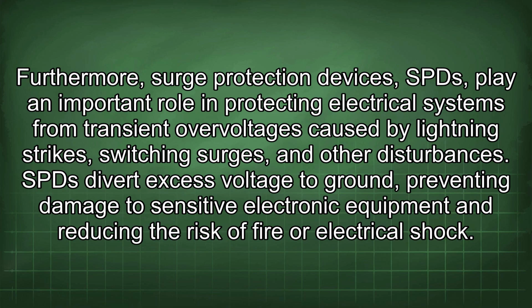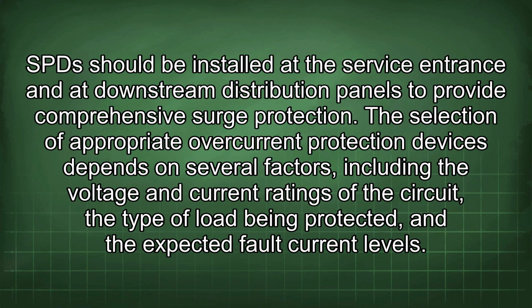SPDs divert excess voltage to ground, preventing damage to sensitive electronic equipment and reducing the risk of fire or electrical shock. SPDs should be installed at the service entrance and at downstream distribution panels to provide comprehensive surge protection. The selection of appropriate overcurrent protection devices depends on several factors, including the voltage and current ratings of the circuit, the type of load being protected, and the expected fault current levels.